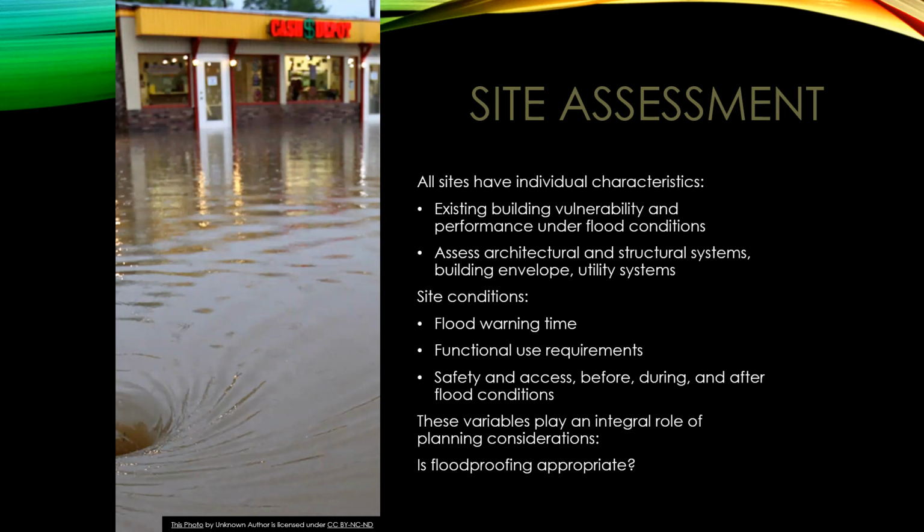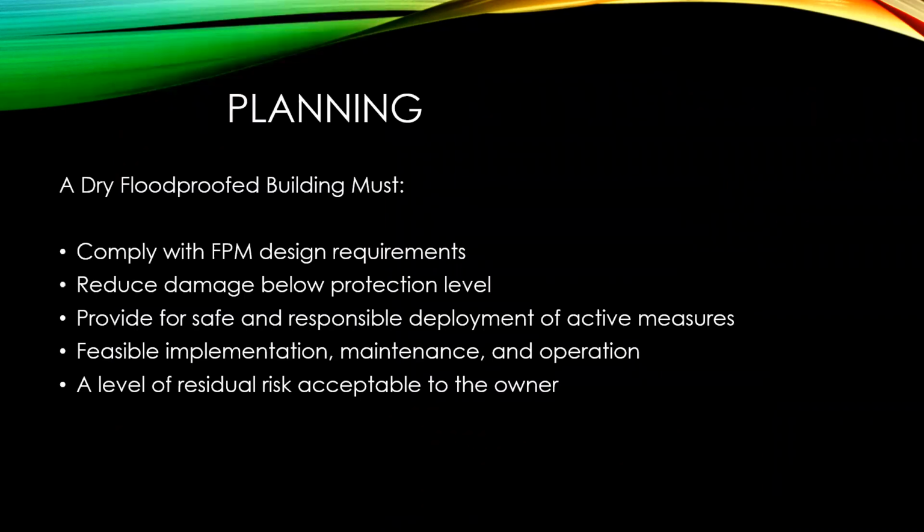And then once we consider all of this, maybe floodproofing is not going to work for us and we should rather elevate. And most people choose to elevate because, again, this is very complicated and it's a very big undertaking to try to dry floodproof a system.